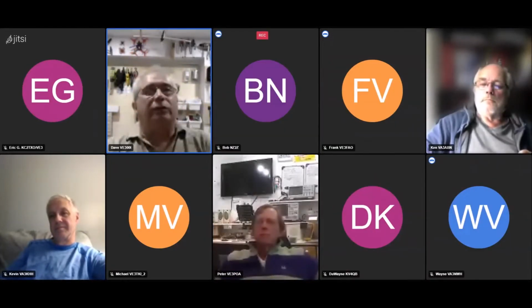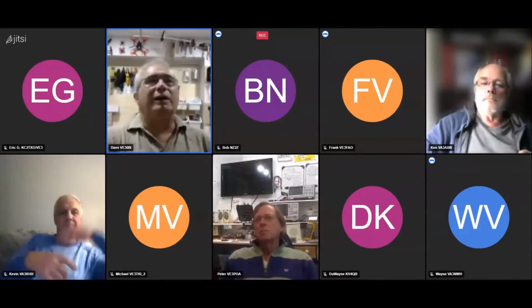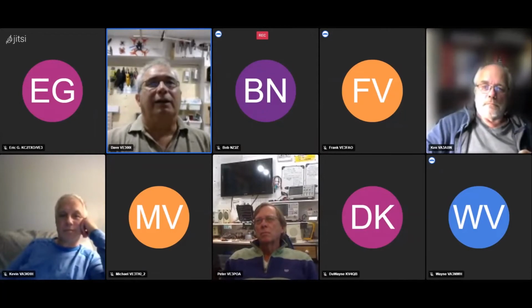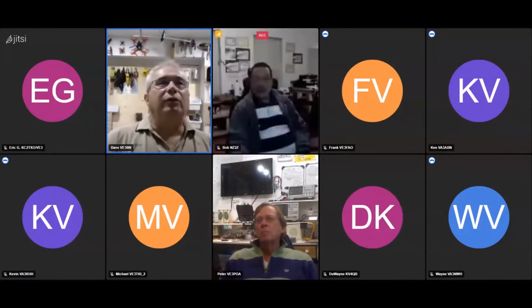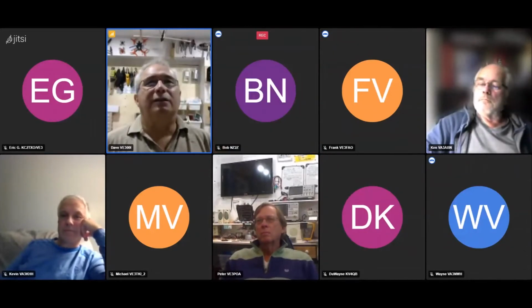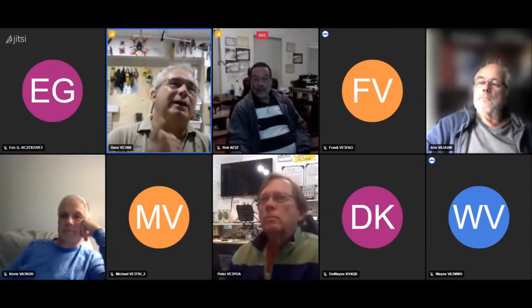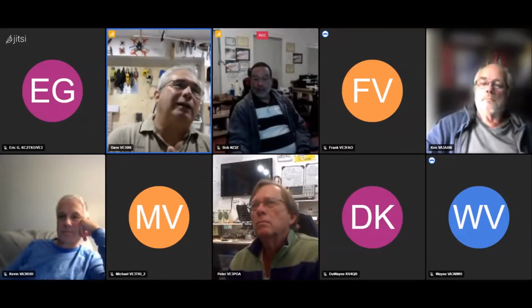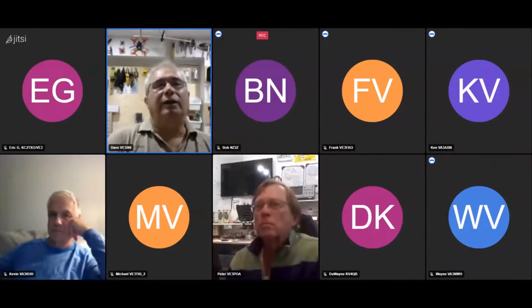Yeah, he does. He goes on to say there are calculators you can get as well. He was showing all kinds of online calculators, like what Kevin's saying, where if you want to get the right impedance for the trace, you put in the parameters: the ground plane below it or above it, the dielectric constant, the width of the trace, the thickness of the copper too. You put all that stuff in the calculator and it spits it out. And I believe KiCad has that calculator in it. If you go into tools, you'll see it's got calculators there.